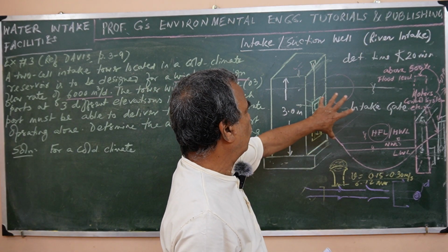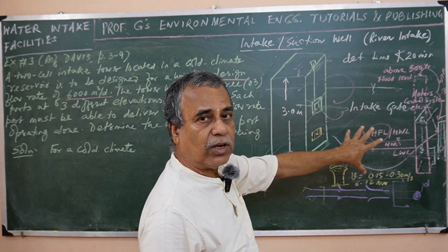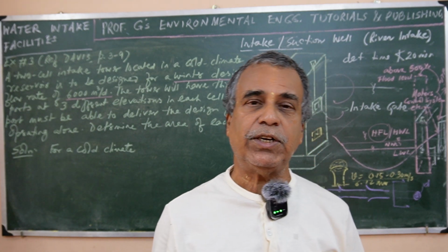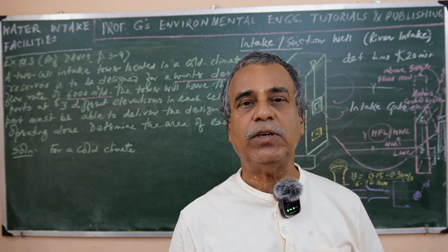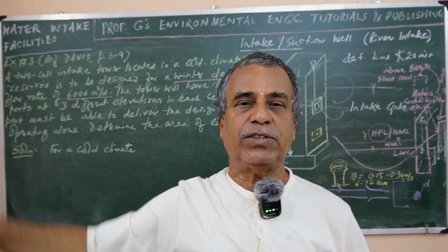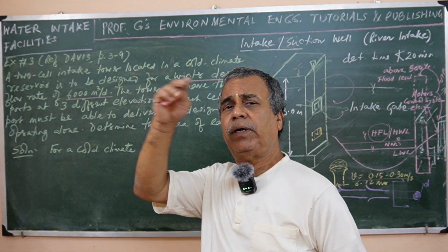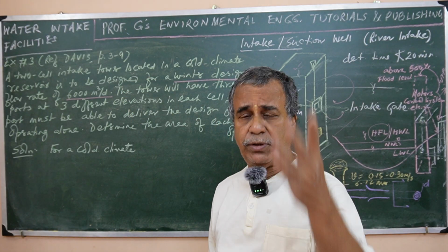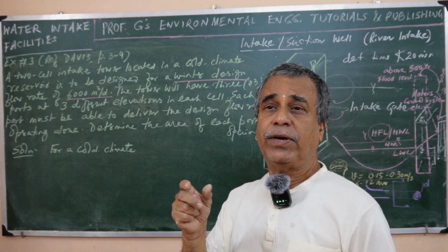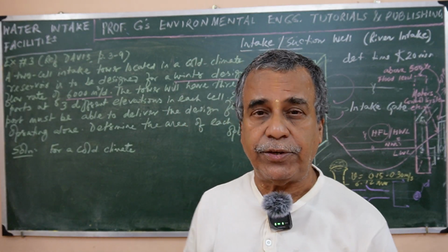That means which phase gives lesser current, which phase will have less turbulence, and which towers will actually allow sufficient water during the worst condition. That also has to be considered. And for the highest flood levels, suppose when turbulence is on the surface, the top intake port also has to be quite deep, as I have already told, sometimes 5-6 meters below the surface, so that the turbulence or debris do not damage the gate, right?